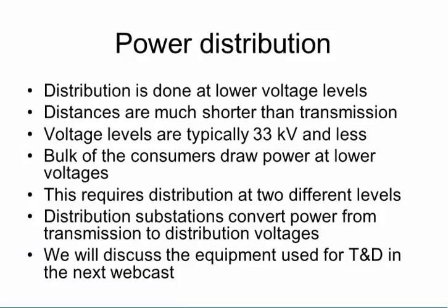Now the next part, which is the step after the transmission side, is what is referred to as distribution, and it generally occurs at, now, the generation of electricity under coal fire or turbine driven generation is roughly between the 11 kV and the 30 kV voltage level. That's coming straight off a generator. The voltage then gets transformed higher to allow the transmission over greater distances.